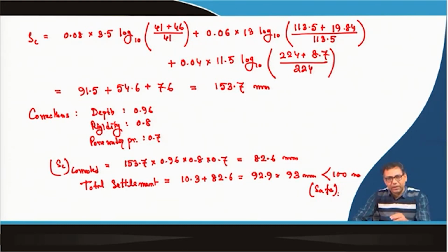But remember that sometimes only the beam concept is not sufficient, you have to go for the plate also, but the concept is similar. You can use it for strip foundation and combined footing, but sometimes you have to extend your beams on elastic foundation concept to plates on elastic foundation by using the same concept. So, you remember that before you do the check considering soil foundation interaction.